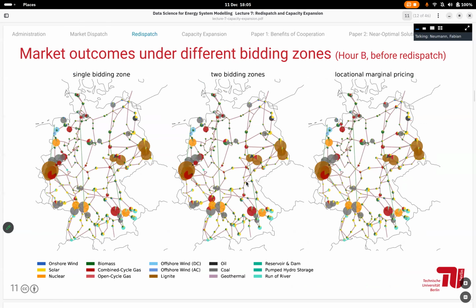So in terms of the optimization model, in terms of math, this is what you already know. This is the optimization problem we had in one of the previous lectures: the energy balance and the generator limits, storage limits, storage consistency equations, and the line limits, as well as Kirchhoff voltage law, with the decision variables in red. What we now have is a slightly expanded model that in principle doesn't change, but we have new investment decision variables in blue.